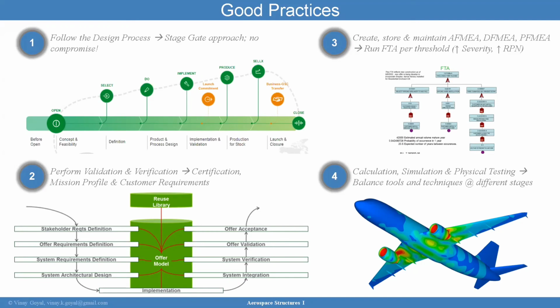So in this case, you would have the chief engineer of the structural frame of the aircraft, right? You will have the propulsion specialist. You will have the aerodynamics and control guy. You will have the electrical and navigation guy. Very, very important to have that synergy, synchronization. And again, the test plan at the end of the day will have to be built up in such a fashion that you test at component level, at subsystem level, and at system level.